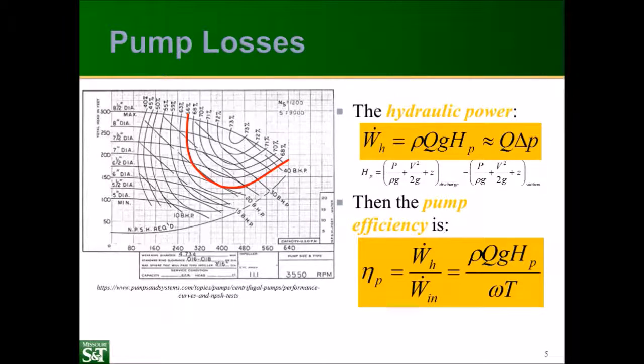So if we're looking for a particular head and flow combination, say we have a 400 GPM flow rate and we need 200 feet of head. So we go to our 400 GPM flow rate and we go up until we reach 200 feet of head. And we want to pick a pump and figure out what the system is going to look like. So here we can't use the 7.5-inch diameter rotor because it wouldn't produce either the flow rate or the head we want.